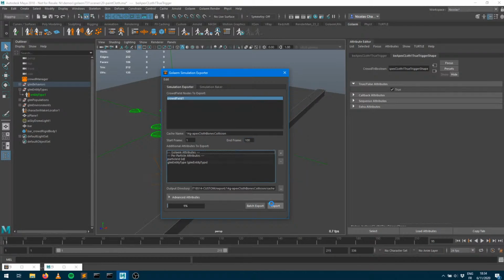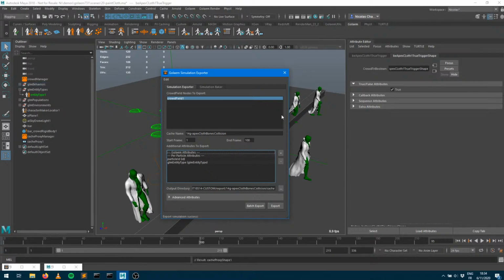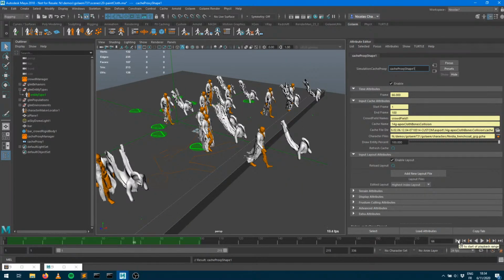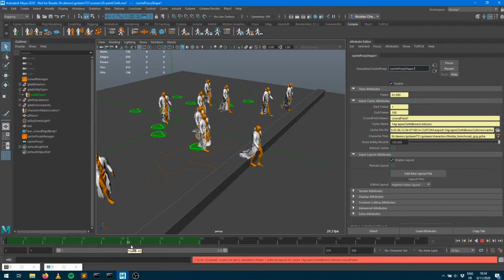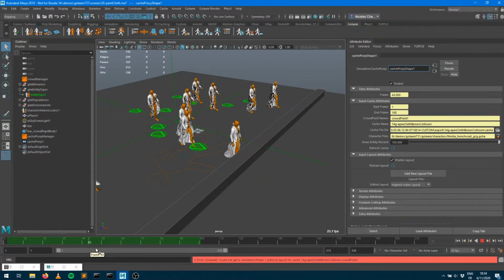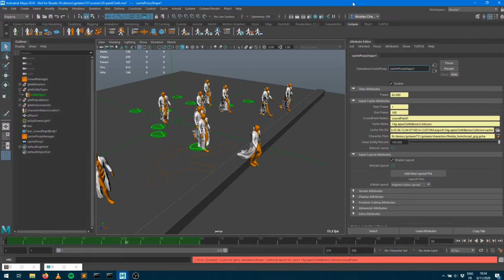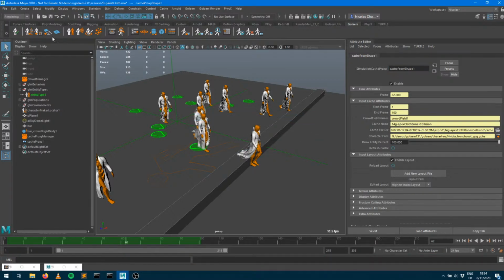So I just enable the cloth really at the end, because it takes some resources to actually compute those cloths, and I don't want to spend too much time in that computation while I don't need it. And when it's exported, you can see the result of that. You still have the simulation result, so we still need to go to frame 0 to remove that. And you can see that now that cloth stuff appears in cache replay. You can manipulate your characters with layout, move them elsewhere, and you also get that cloth being followed, but no more simulation, right? And just to make my point about rendering here, I'm gonna render that.